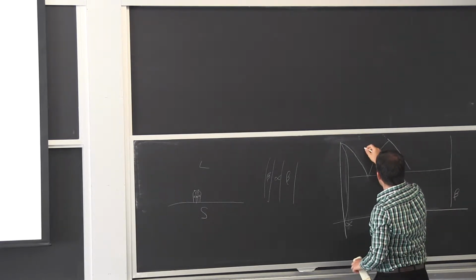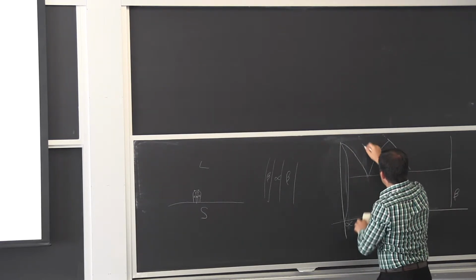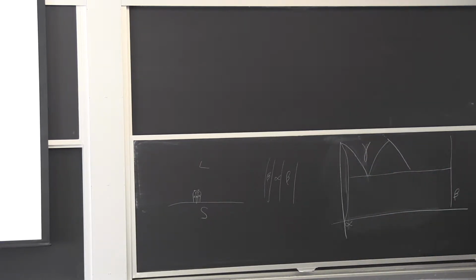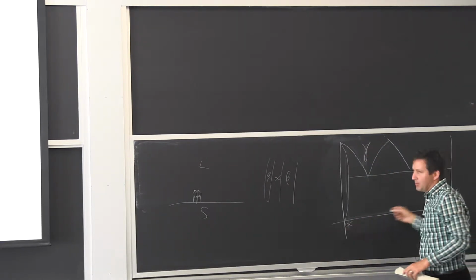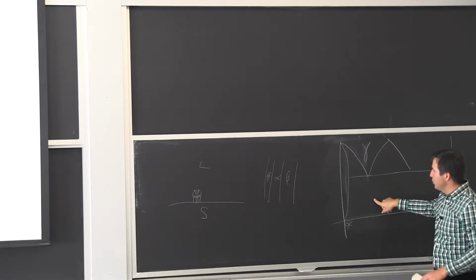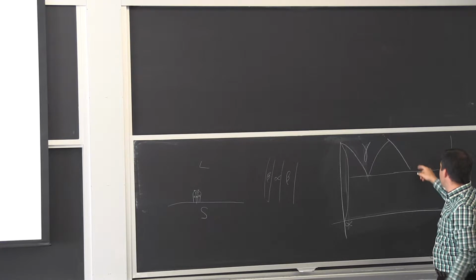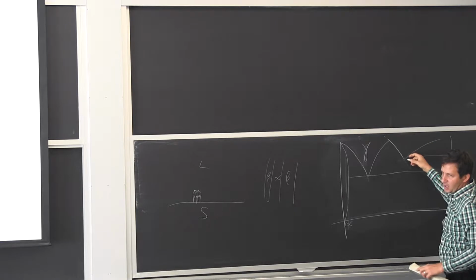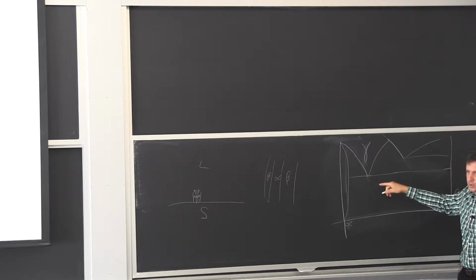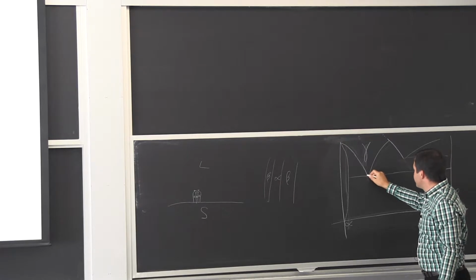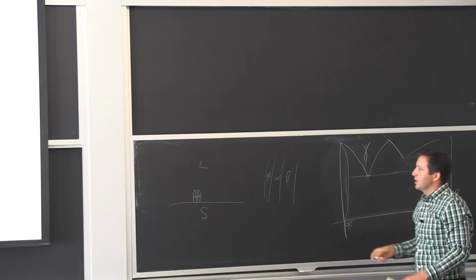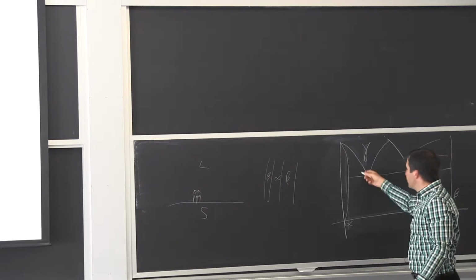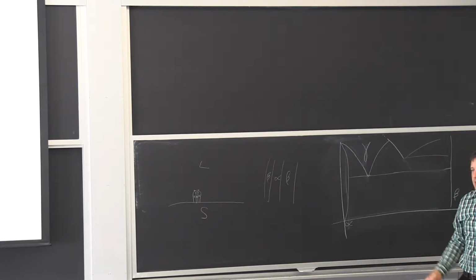Okay, so over here, you have a solid, that's the austenite, that's red steel, that's going to transform into the cementite. So one phase going into two phase, but instead of being a liquid, like we have over there with the cast iron at a higher temperature, you're having it at a lower temperature, everything is already solid. And typically for steel, if you're really going to soften it to go to a subsequent process, you go back here and essentially recrystallize at that point. It's all blended together, and then you cool it down again and go for it again.